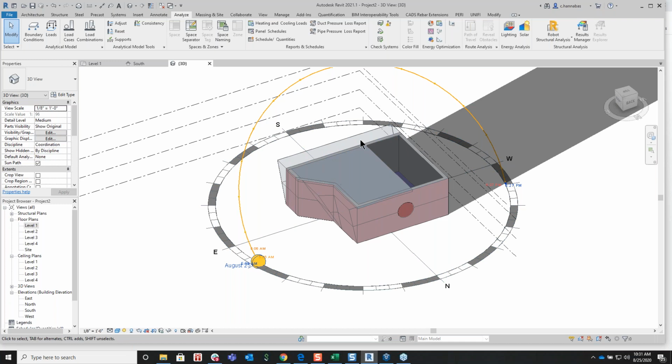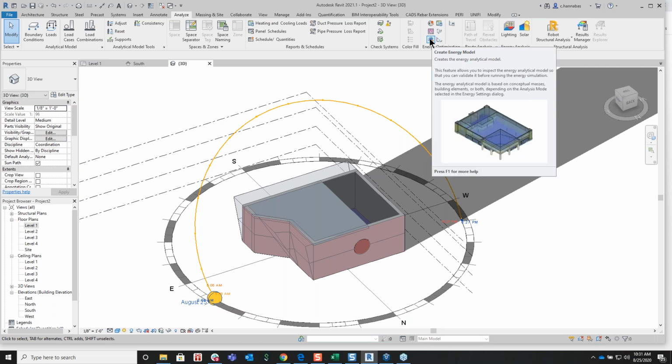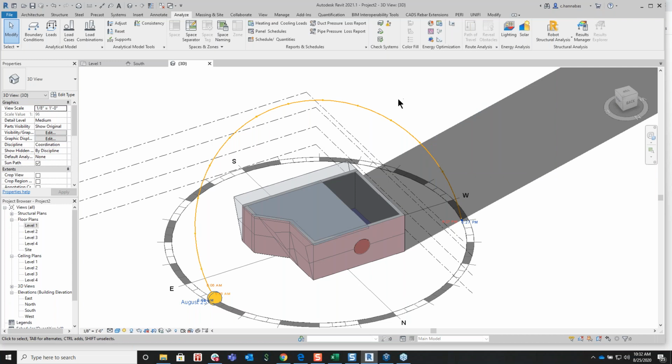We use Energy Plus to do all our analysis, just like all the third-party applications. So within Revit, when you do your energy analysis, it automatically sends it out to Energy Plus to have the analysis done. And again, you can adjust settings. That's a whole other class on doing that in the solar studies. But yes, we can do all that with just the mass itself.